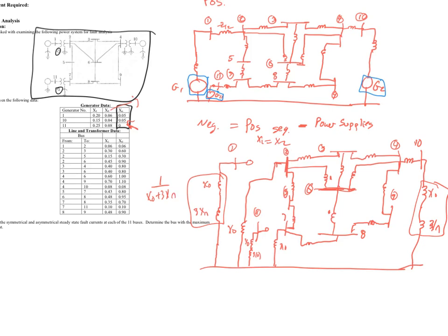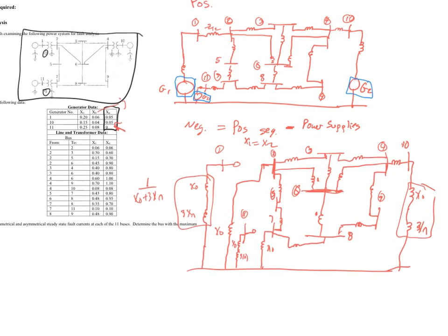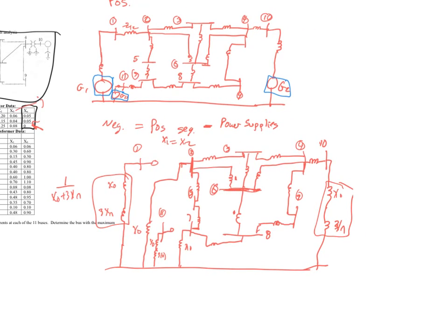You cannot invert them first and then go ahead and convert those and get the Y buses correctly. So now you have enough information to go ahead and build your Y buses. You should go ahead and invert. Make a little more room here. We should now invert all impedances to admittances.